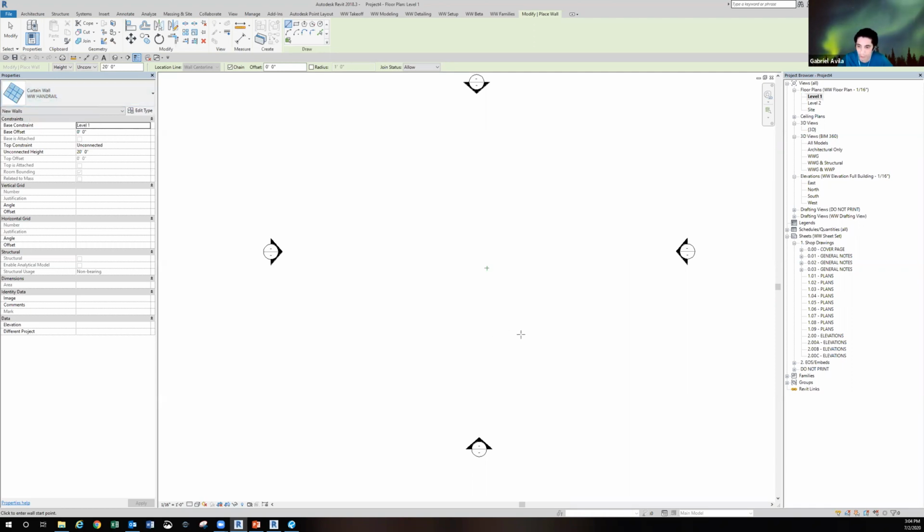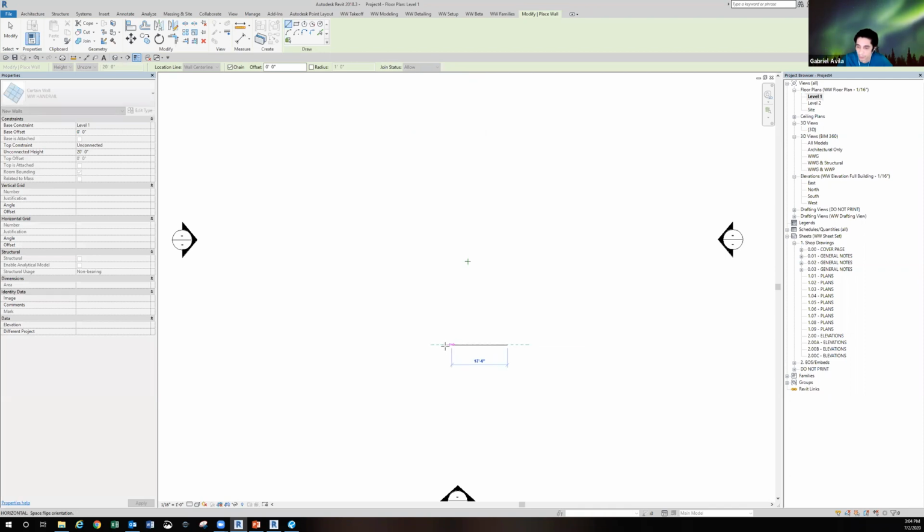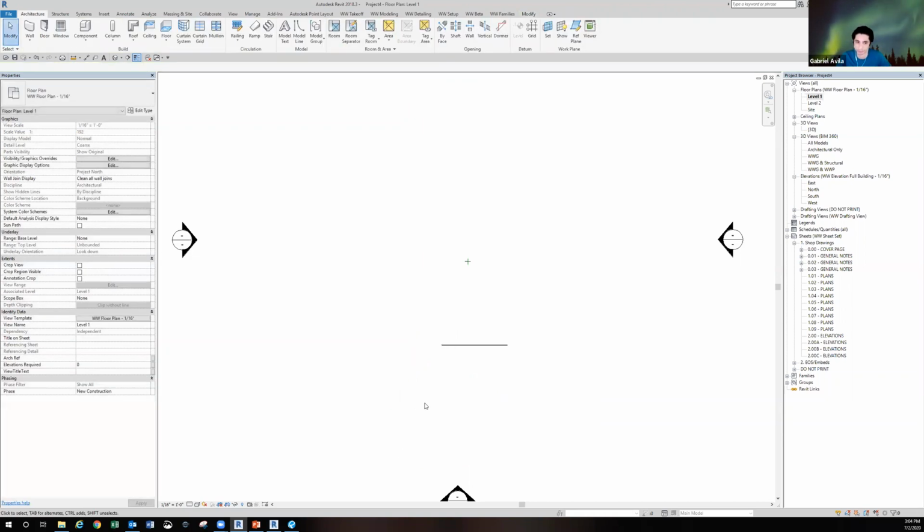So you can either go ahead and start placing, pick your 2 points, or you can set the height of it first. I like to pick the points and then I can adjust it later, but it depends on your preference. So say I want to build a handrail here. I can click on my first starting point. And you remember to go clockwise. So I'm going to start on the right side, go over to the left. Say this is 20 feet. Just double click there again and hit escape twice. So there is my handrail, where it's going to be placed.